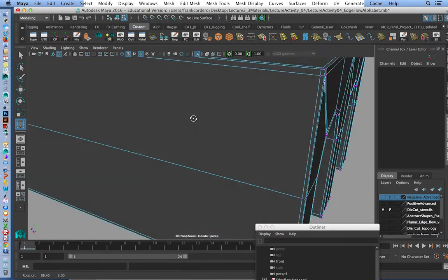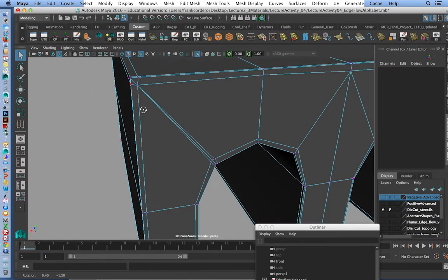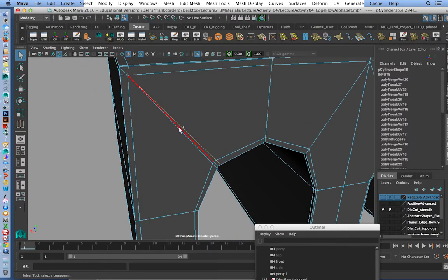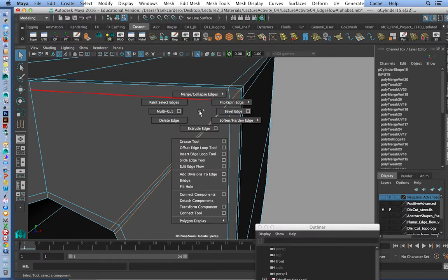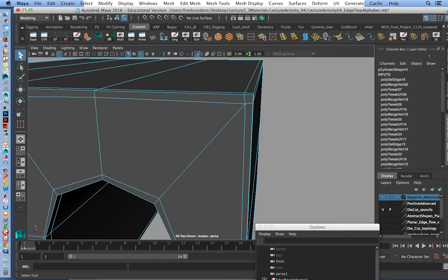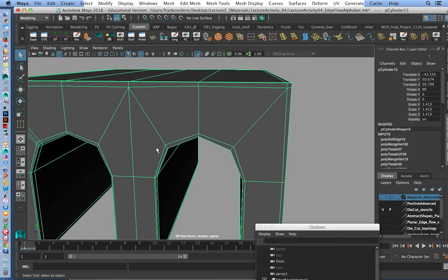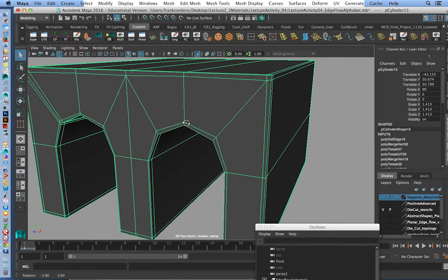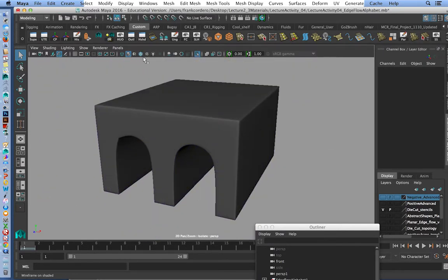So I'm going to go over here, target weld. So again, I want to keep the holding edges working on this corner, but then terminate their use over here. Same here. So now I'm going to go ahead here, delete, delete, select that edge too, and then select that edge, and then delete edge vertex, and now I'm left with a much cleaner solution. So the holding edge is working on this outside area, all right? And over here, we're getting this cleaned up.